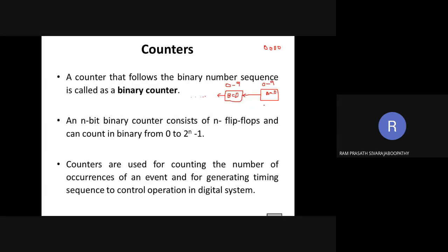Fine. So here we'll be having 4-bit outputs. Here also we'll be having 4-bit output. So here we are providing the clock. Sorry, the output of the BCD counter is given as clock to the next digit. So what happened? Initially the count changes from 0 to 9. Once it reaches 9, for the next count, what must be the value it has to go? Again, it has to go 0, 0, 0.